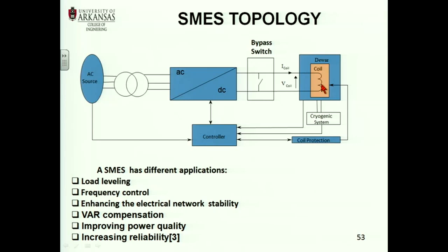So anytime you need a constant voltage, you put an output capacitor. If you go back to your experiments or your senior design 1, if you have built an electronic circuit with an op-amp, what do you have at the output? A filter capacitor, because the function is to have a 5-volt or 15-volt power supply.